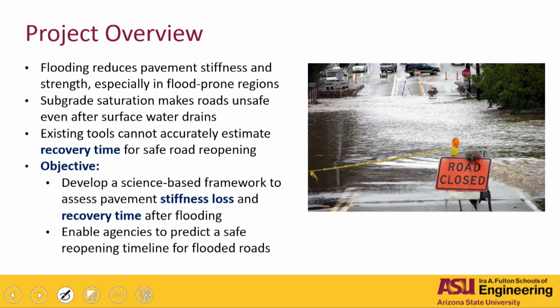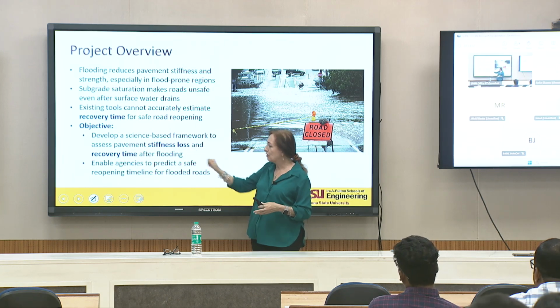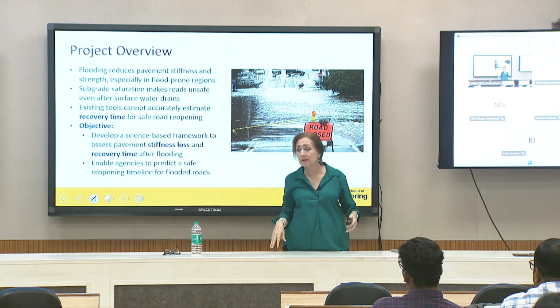So our objective, this is just part of a project that we are finalizing and is getting very nice results, was to develop a science-based or a mechanistic-based framework to assess the stiffness loss or the resilient modulus reduction, but also the recovery time after the flooding, to see how much time you need to open the road.